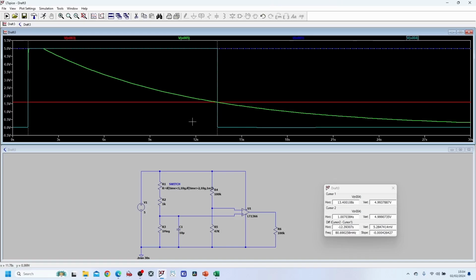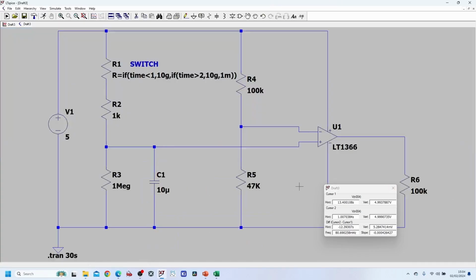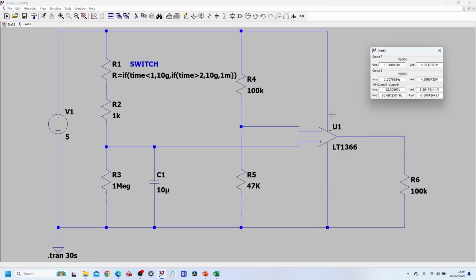The values that you see on this circuit here are the values I have available. I don't have this op amp, but I will be using a different op amp, LM358. I did have a comparator, LM393. However, I think I may have a bad batch, as this didn't work with the circuit that I was showing you here. So let me show you how I build up the circuit and then the timing diagrams and everything.